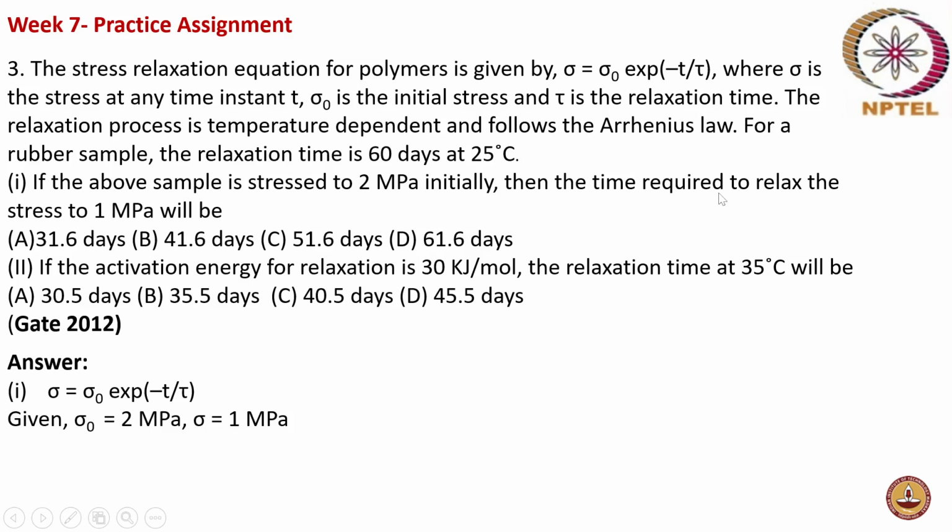Then the time required to relax the stress to 1 megapascal. So the final stress is 1 megapascal. And they have given a stress relaxation experiment. That means a constant strain is applied, so the stress decreases with time. They have also given the relaxation time is 60 days at 25 degrees centigrade.